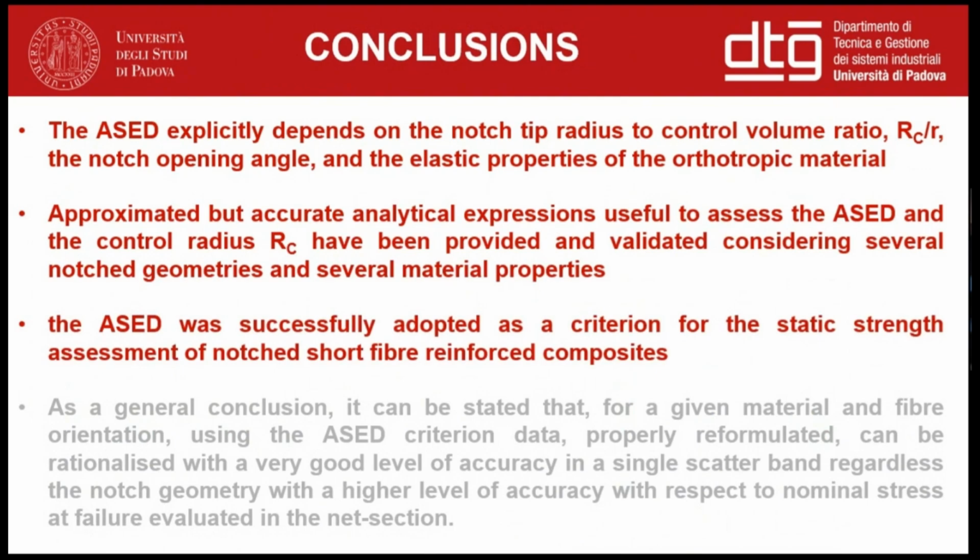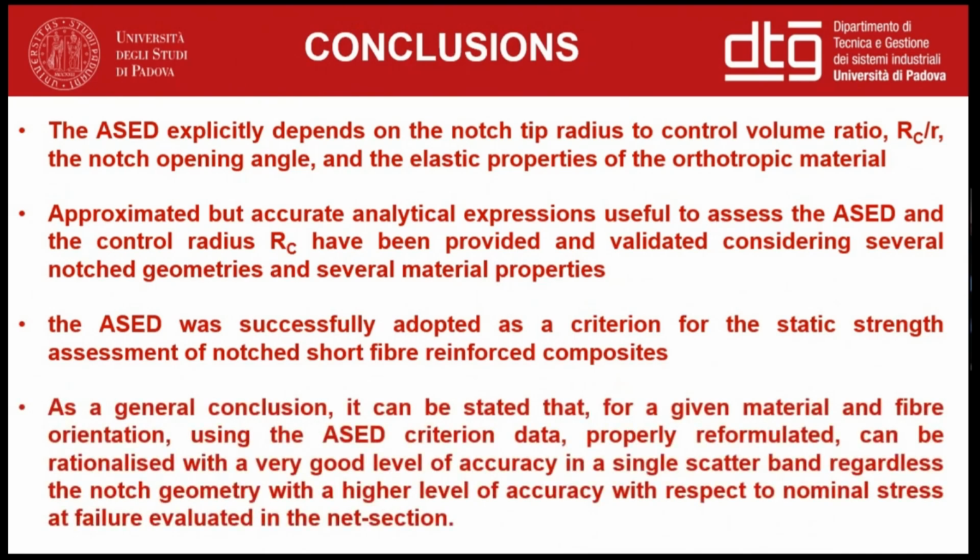We have validated this expression numerically, comparing with numerical data, and we have applied the criterion in order to assess the static strength of notched short fiber reinforced composites. And as a main conclusion, I would like to state that this criterion, which was formulated more than 20 years ago for isotropic material, has appeared to be very effective also for this class of materials, composite materials, which are very complex because they are characterized by a very complex morphology.